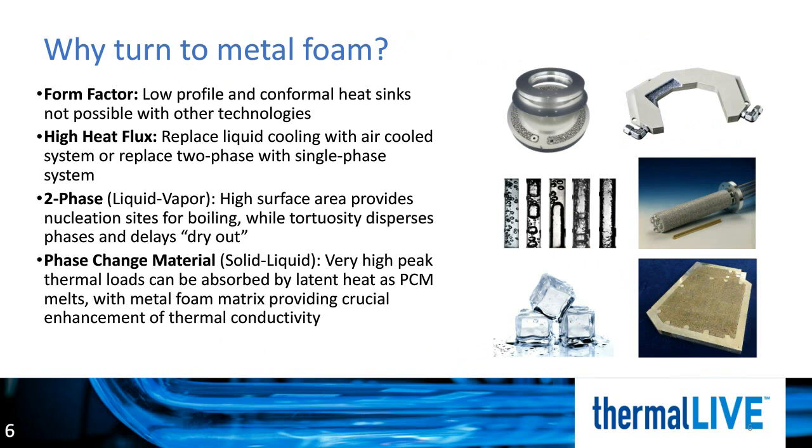Metal foams perform well when current technology doesn't quite provide enough cooling. Metal foams work particularly well when there are unique constraints on form factor, such as low volume requirements, low profile requirements, or conformal geometry constraints. Metal foams should be considered when heat fluxes are high and there is an advantage to simplifying the cooling scheme. For example, replacing liquid cooling with an air-cooled system, or replacing a two-phase system with a single-phase cooling system.